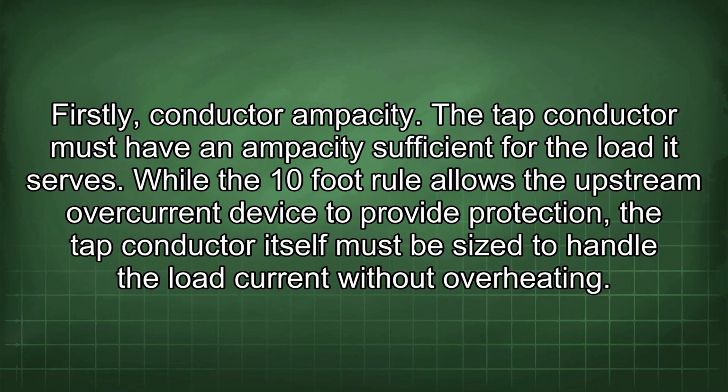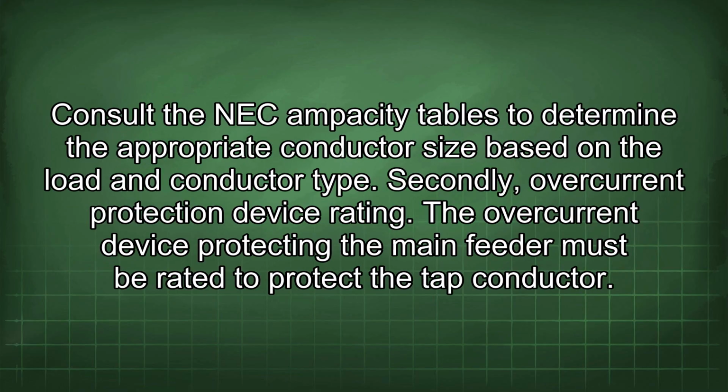Firstly, conductor ampacity. The tap conductor must have an ampacity sufficient for the load it serves. While the 10-foot rule allows the upstream overcurrent device to provide protection, the tap conductor itself must be sized to handle the load current without overheating. Consult the NEC ampacity tables to determine the appropriate conductor size based on the load and conductor type.